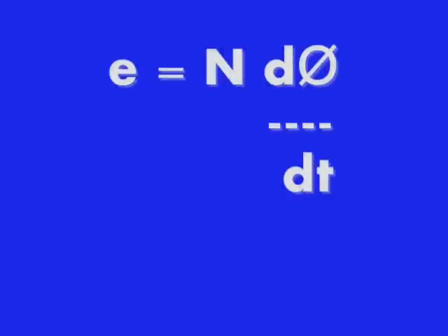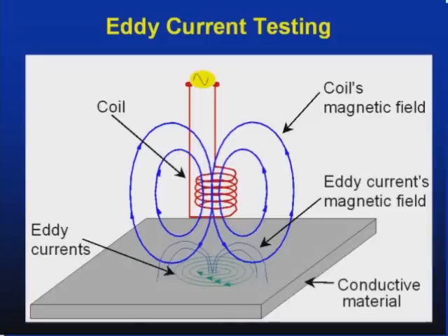According to Faraday's law, the voltage E across the coil is E equals N delta flux over delta T. Now I will give you more information about eddy current loss, which you already know a little bit from the previous chapter. Eddy current loss occurs when the flux density changes rapidly in the core. The time variation of flux generates an induced voltage, and the current inside the core is eddy current. A power loss I squared R will be caused by the eddy current and will appear as heat in the core, because the core material has resistance.